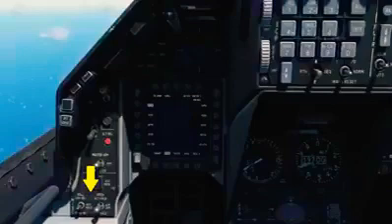The roll switch includes a heading select setting to have the aircraft turn to and maintain the heading select bug on the HSI. Attitude hold maintains the current roll and pitch attitude, and steer select directs the autopilot to steer to the selected steerpoint as selected from the DED. Both switches can be used in unison.